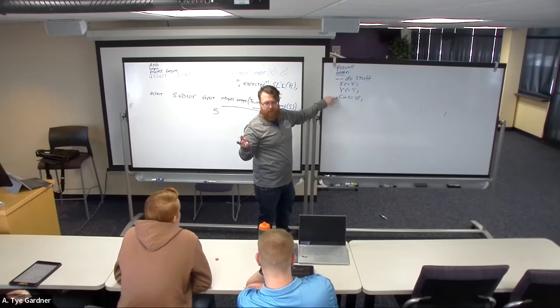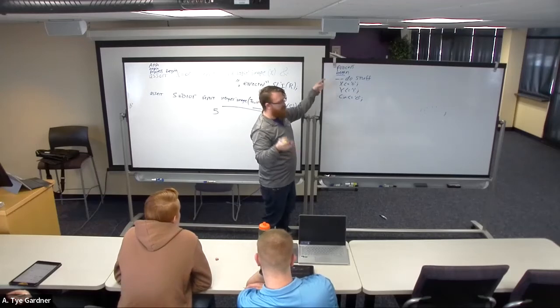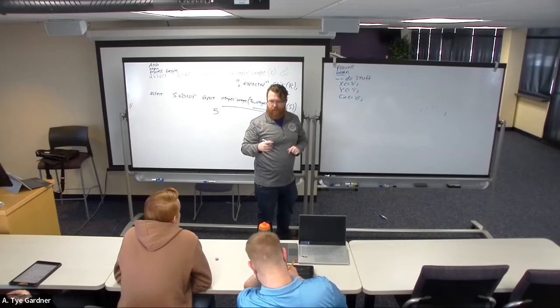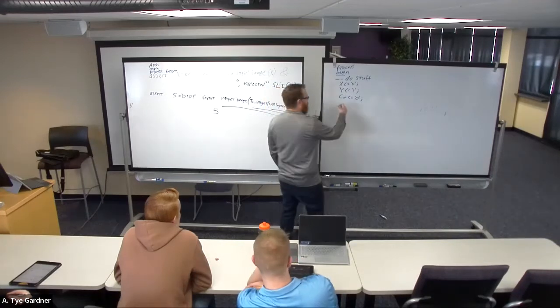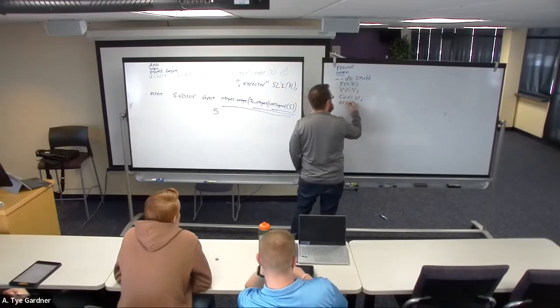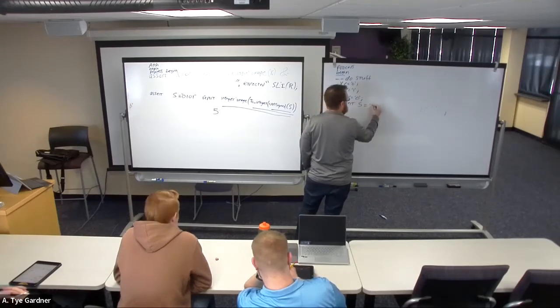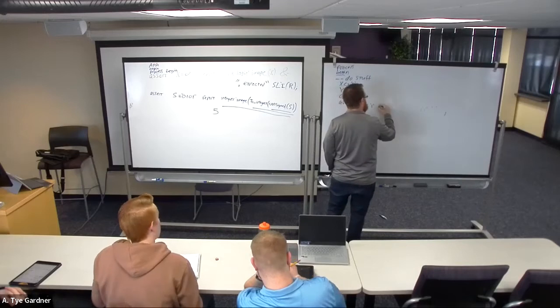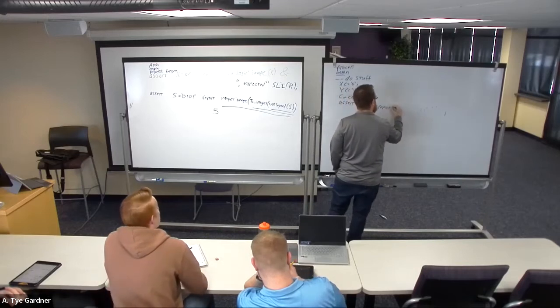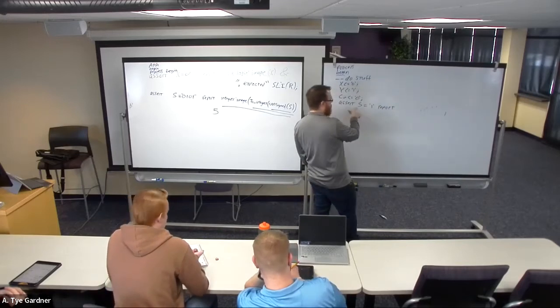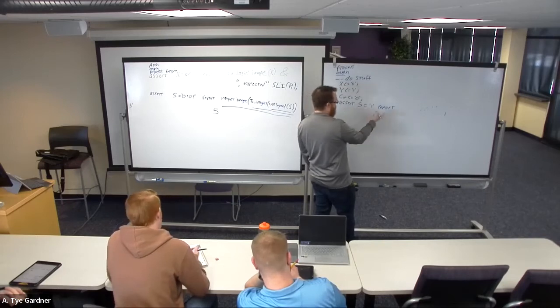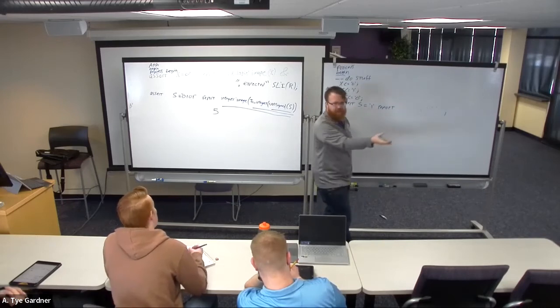And I can look at what the outputs are. Hopefully my sum is 1 and my carry out is 0. So then I would just go ahead and write assert sum equals 1. Report assert sum is 1. Report, I could say error bad sum, right?